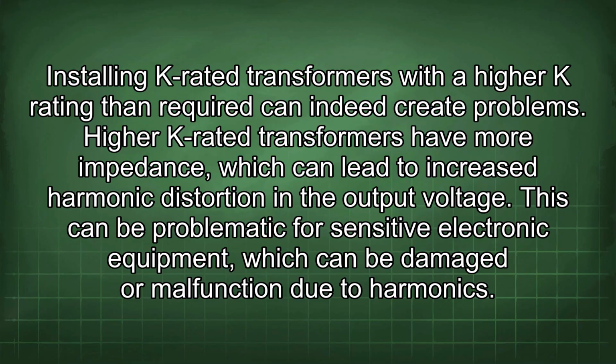Installing K-rated transformers with a higher K rating than required can indeed create problems. Higher K-rated transformers have more impedance, which can lead to increased harmonic distortion in the output voltage. This can be problematic for sensitive electronic equipment, which can be damaged or malfunction due to harmonics.